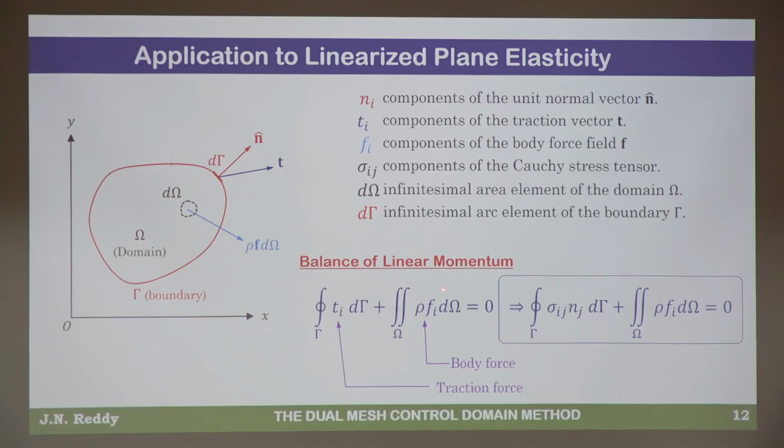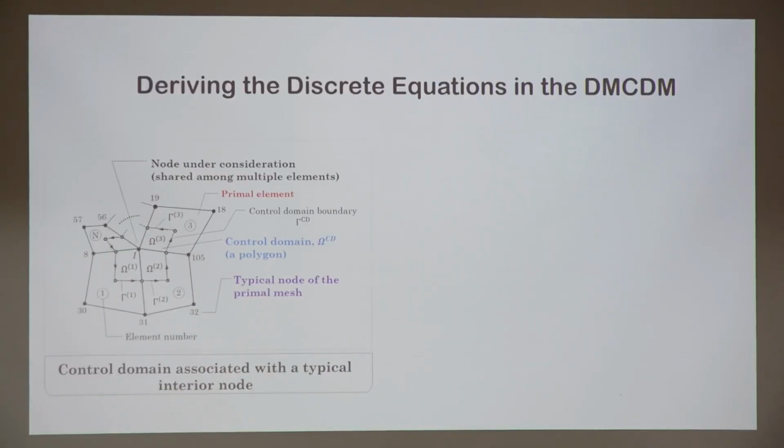So, and this is the body force. I'm showing that when I replace T_i using Cauchy's formula, you get this expression. Then you can use the constitutive law to replace the stress tensor components in terms of the strains, in terms of displacement gradients. All of that they do and I do. The only difference is their gradients are replaced with Taylor series. Here they are replaced with the interpolation derivatives. Okay? So we do reduce the dimension by 1.